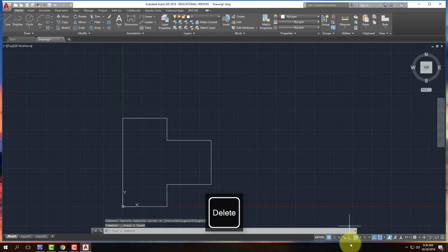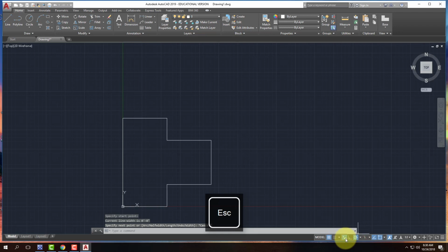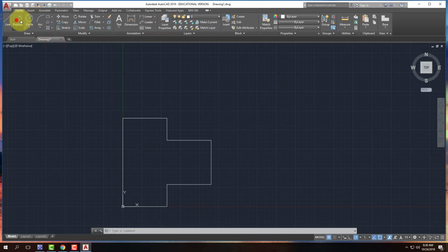The truth is, though, most of you will leave dynamic input turned on. So I'll go ahead and click the plus sign with the box next to it to turn dynamic input back on. And this changes a little bit in how we draw. So if I were drawing this shape again, I'm just going to draw it over here for illustration purposes. At this point, you see that instead of having, let me turn dynamic input off and do that one more time. Oops. Hold on. Sorry, I lost my tools here. When I'm drawing, see how I have no input text boxes next to my cursor as I'm drawing?